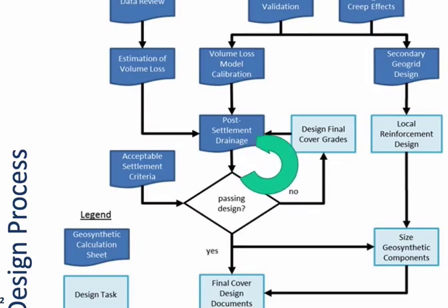We went to a more generalized model that's essentially like a tunneling deformation spreading model for the site-wide analysis over the 24-hectare site. And that was highly simplified. The reason for doing that was so that we could run hundreds or thousands of realizations with a random field model where we were simply altering the occurrence of those void collapses inside the waste trenches across the entire site. So, long answer to a short question. We started out at the small scale using more sophisticated numerical analyses. We went to more simplified numerical analyses at the site scale once we were convinced that they had been adequately calibrated. I hope that answers your question.